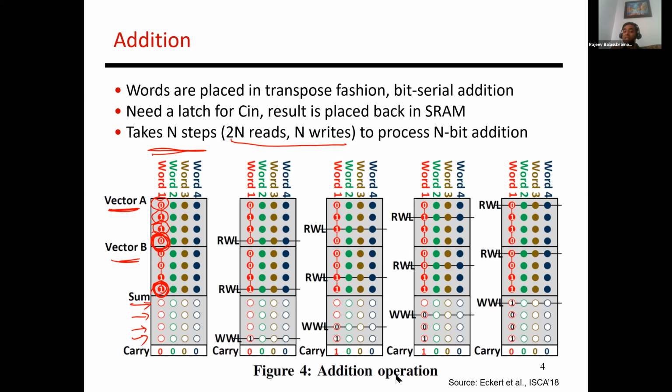The sense amplifier does have to be modified. So I think on the very next slide, I talk about the few changes required to the sense amplifier. And so essentially, yes, the circuit does need some changes in order for this to work well. But there is not the concern with destructive reads as there is in DRAM, right? So the next design I'm going to talk about is DRAM operations, and there, yes, the operations are destructive. Okay, but here that concern does not exist.